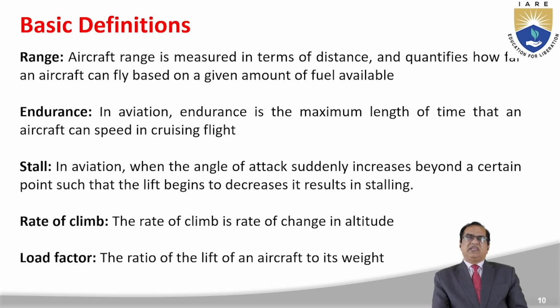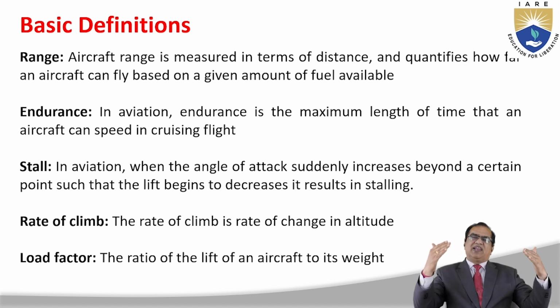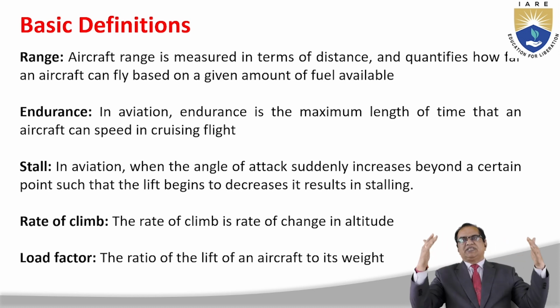Stall, in aviation, is when the angle of attack suddenly increases beyond a certain point such that the lift begins to decrease, which results in stalling. So as you increase the angle of attack, for a certain angle of attack your lift will be increasing.